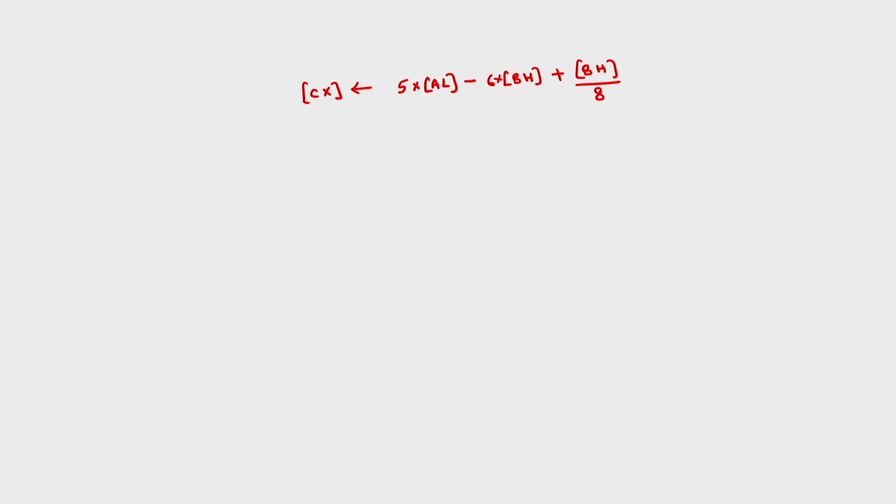Okay. So, I am assuming the same data segment contains 5000H, MOV AX comma 5000, MOV DS comma AX, then you compute this step by step. Okay. 5 into AL. Okay. So, you have to take 5 into some register, say MOV BL comma 05H. Then let us assume that these numbers are unsigned numbers.